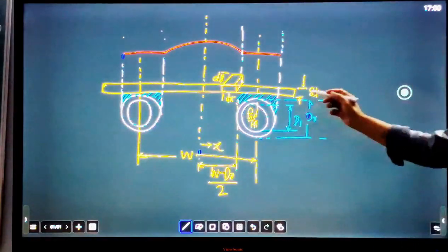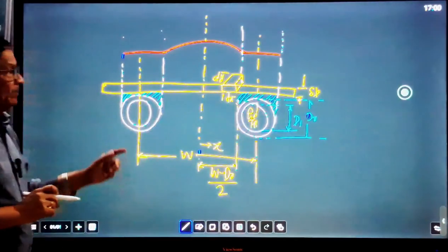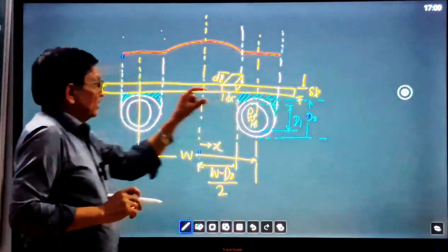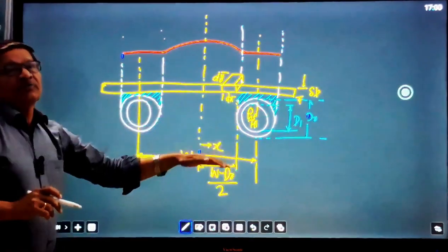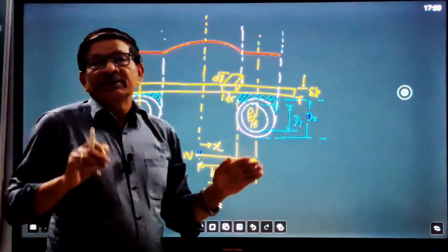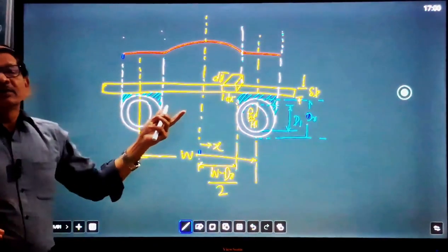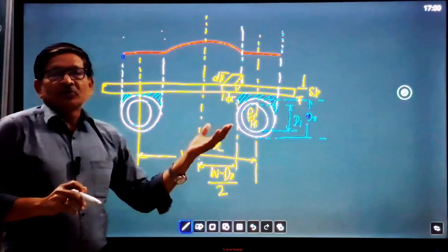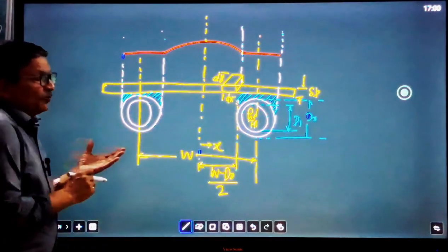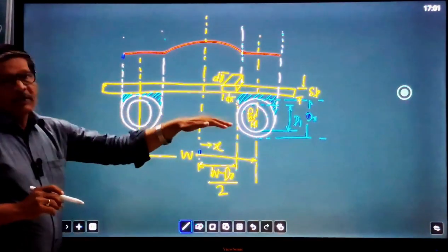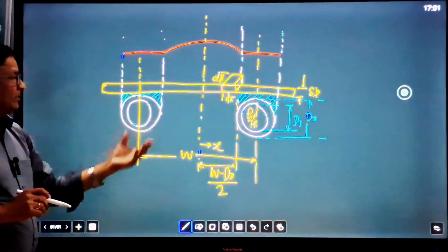So see here, this is the absorber plate having thickness del P. This is the absorber plate inside the collector. These are two tubes below the absorber plate. Because there are two arrangements, this is fin type arrangement: either tubes are above the absorber plate or tubes are below the absorber plate. We are taking two tubes, and the width of the tubes is along the width, because along the length there will be length of the tubes.